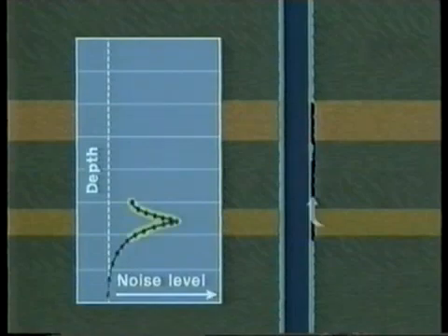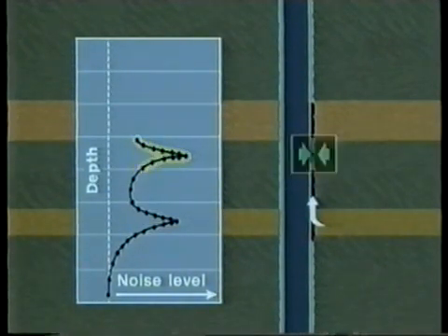The second category of qualitative fluid movement detection devices is the borehole noise survey. Noise surveys detect fluid flow downhole by the sound it generates. Noise logging tools detect noise generated either inside or outside of the wellbore, and most are designed to be run in a stationary mode. Both fluid movement and pressure drop are required for the noise to be generated. Noise amplitude is greatest at the point of entry from the formation and at the point of restriction of flow.